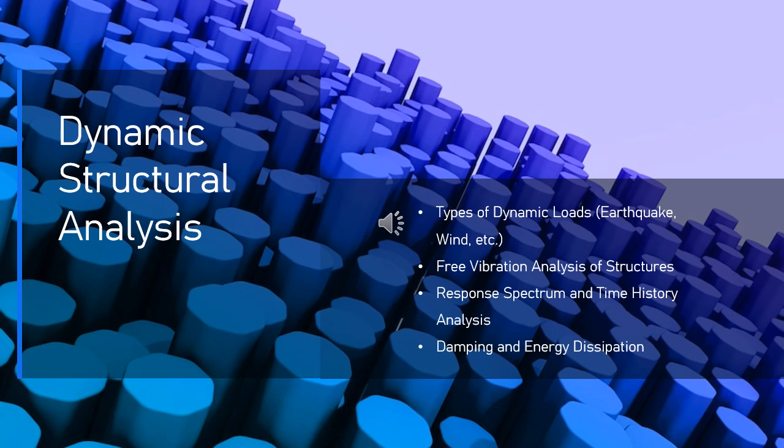Accuracy. It is more accurate than RSA because it solves the exact equations of motion over time, capturing the full time-dependent response of the structure. Detailed results. It provides detailed information about the structure's response, including maximum displacements, velocities, accelerations, and forces over time.